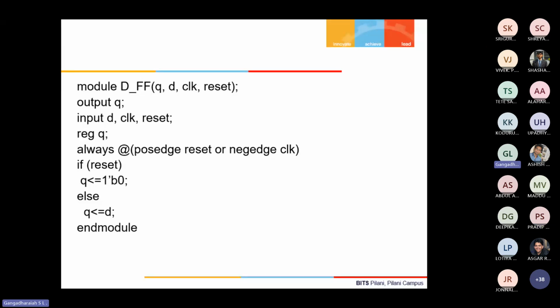Sir, I want to add one more thing here. Synthesis has two types, logical and physical. If we give physical input, like when I do the floorplan and give the input to synthesis, whatever synthesized netlist I get is based on a physical design already done. So if we are doing physical synthesis, we get the physical netlist. But if we are doing logical synthesis, you are not doing any placement, and you get the result with a wire load model.